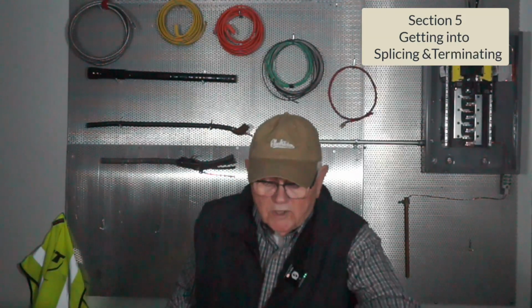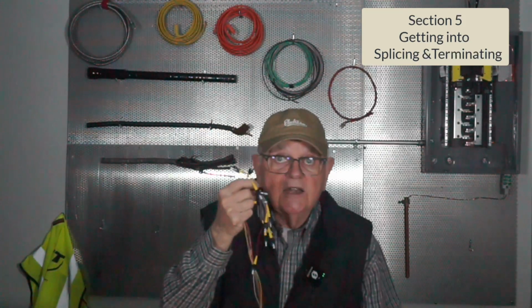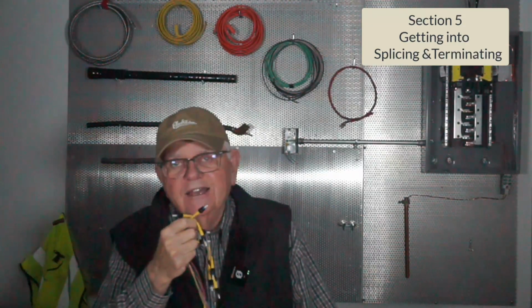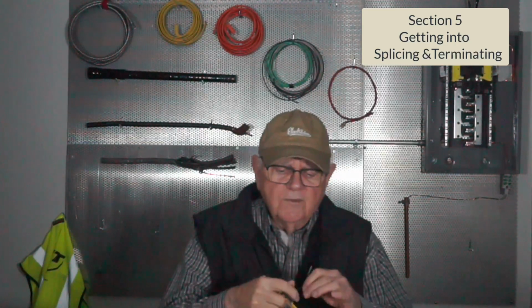Now, before we even talk about terminating and splicing, when you get into it, you're going to be exposing that fine fiber optic core with the cladding, right? And we're talking about the width of a human hair or so. And so very fine. The problem is that glass can become embedded in your skin.